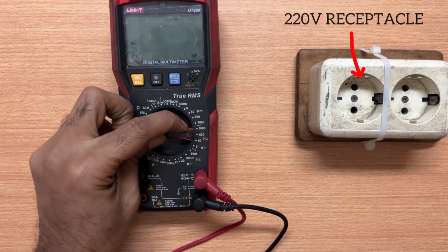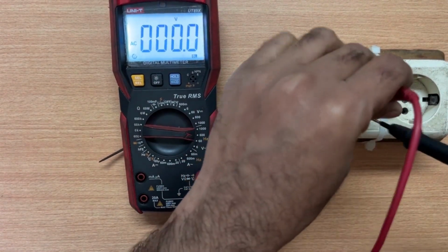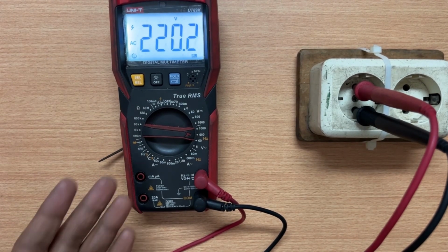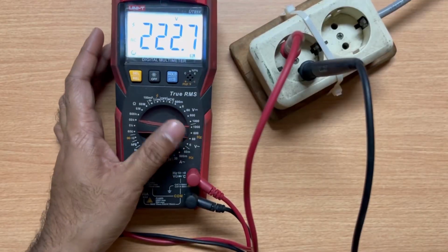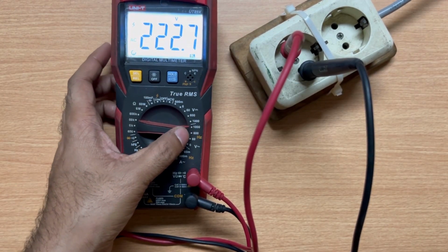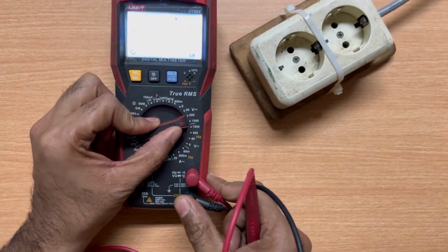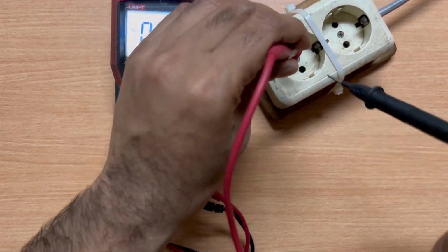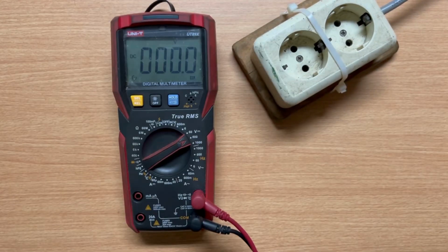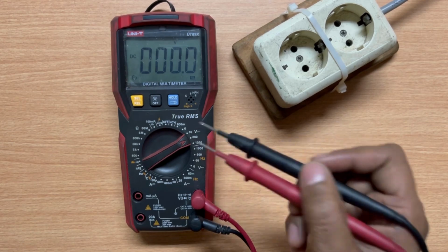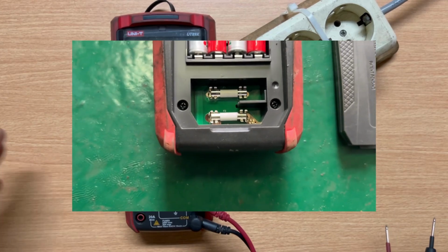If you want to measure 220, select this point, connect your probe at this, insert this, you will see 220 volt. It is showing very clearly. So to measure 220, you have to put it on 600. If you put it on DC by mistake and you measure it, you are not going to get anything. But you must not do it. If I put it on AC and then try to read any DC voltage, it has an inbuilt fuse system. So the safety is inbuilt inside.